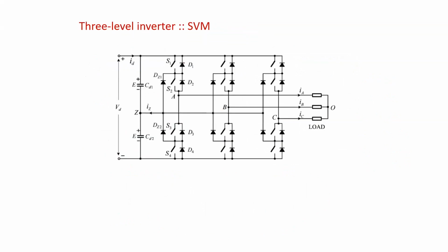So with these things, we'll move on to the next thing. That is the space vector modulation for 3-level inverters. SVM for 3-level inverter. Here the implementation is straightforward. From 2-level onwards, we can directly go for 3-level. The thing is that we have additional switch states, right?